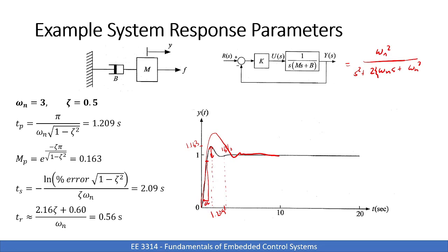For the temperature, we don't want this to overshoot to 200 degrees. So we could say, well, if we set it to 72, maybe an overshoot of 2 degrees is fine, right? So maybe an error of 2 over 72. We want it to get there in maybe a couple of minutes. So we could assign some parameters to that. So when you design your control system, we're not really using these parameters to drive our design in this class. We're mainly using them just as a way to characterize the transient response of different controllers so that we can compare their performance.